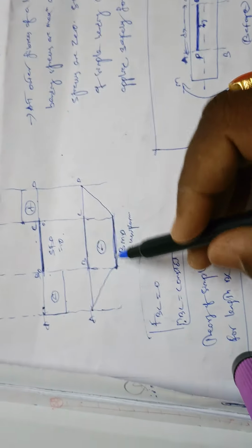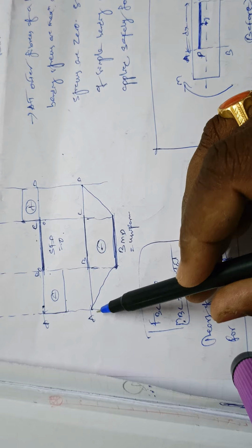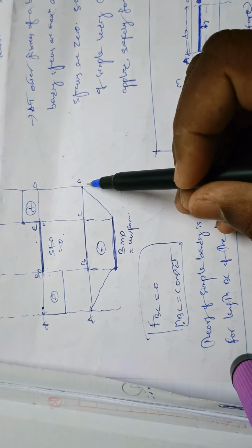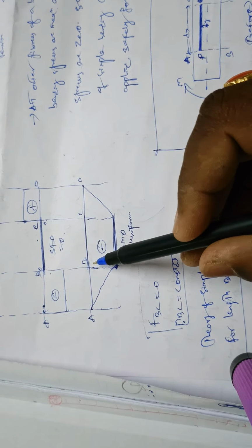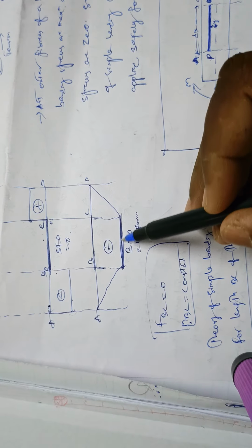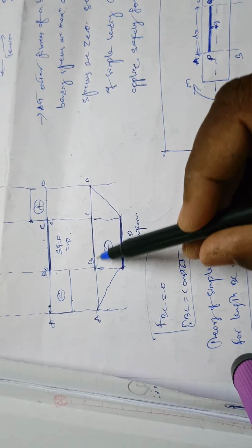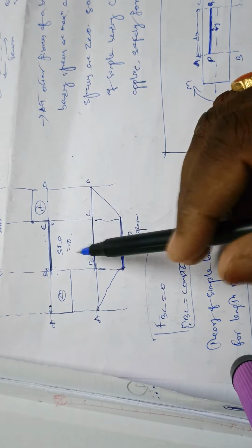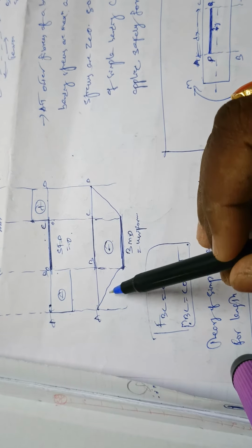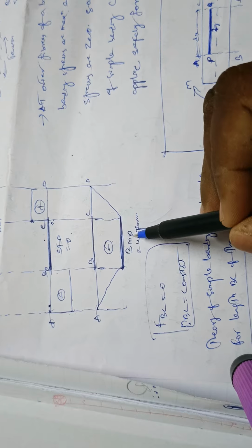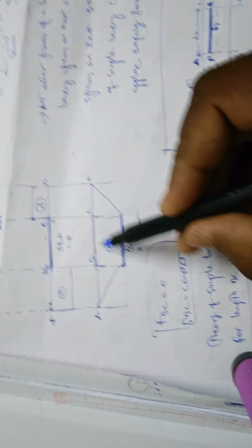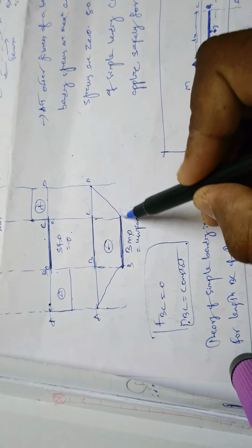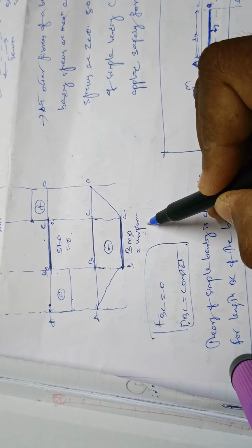Coming to the bending moment, you can see the line drawn here A B C D. Here the moments will be like this. This portion is the bending moment, stated as negative and positive and negative. This is called the BMD. Here also we can see the BC portion is in a uniform condition.